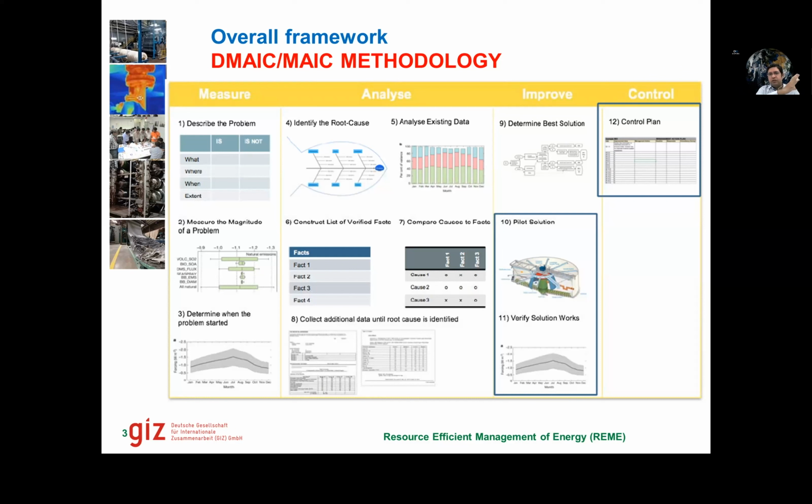Imagine that we have meters installed at all the demand sites wherever steam is being used, and they sum up to 9 tons per hour. So where did this 1 ton per hour of steam go? This is how we can see, based on the data that we have, that 1 month ago we had a difference of only 0.5 tons per hour, and we thought that probably this difference was coming from a difference in measurement of the meters. But now this is increasing, and after a few days we have come to a point where the difference is 1 ton per hour.